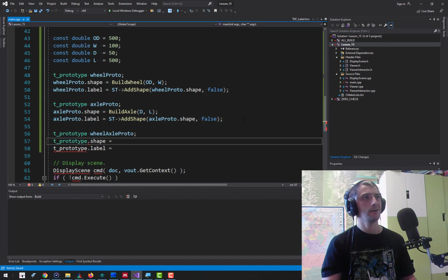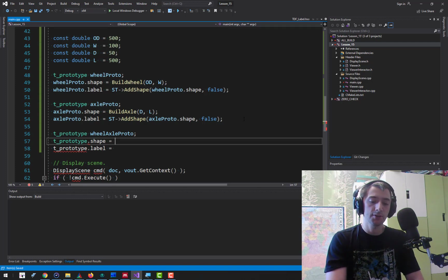And actually here there is one tricky point which is not easy to explain. Why would you need to have a shape for a subassembly? Because if you think about it for a moment, you will shortly realize that a subassembly is simply a hierarchy of already defined shapes. So why would you create another shape? And here, I do not have any good explanation for you. It's a design decision of XDE. In XDE, it's necessary to have shapes for everything.